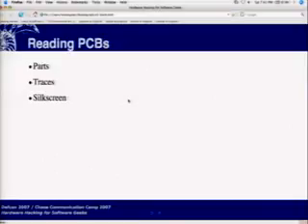I have a monocle sort of display that was set up for PAL, but I opened it up and looked at the circuit board, and I noticed that right next to the resistor that sets this as a PAL video input were a pair of empty pads. Looking at the data sheet, I found out that sets NTSC, and I got it to work better with US equipment as opposed to the rest of the world where they use PAL.